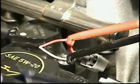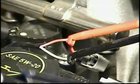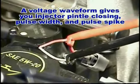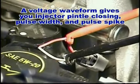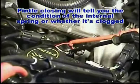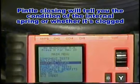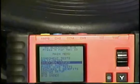Connect the black and red multimeter leads to each one of the injector wires. If the waveform is inverted, simply flip the leads. Here we have the waveform viewer, which is a setting that allows the technician to graph a waveform. An oscilloscope will also do the trick. But you can do the waveform analysis using only the graphing multimeter.